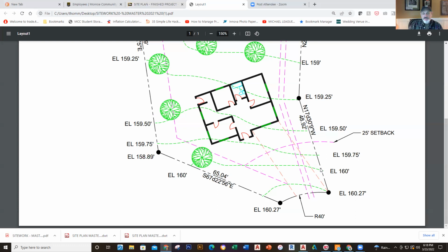So they look different. Now, what this means right here: you see this says N, that means north. And so it says north, 17 degrees, okay? And then 30 minutes and 9 seconds west. Those are all based upon the 360 degrees of the compass.